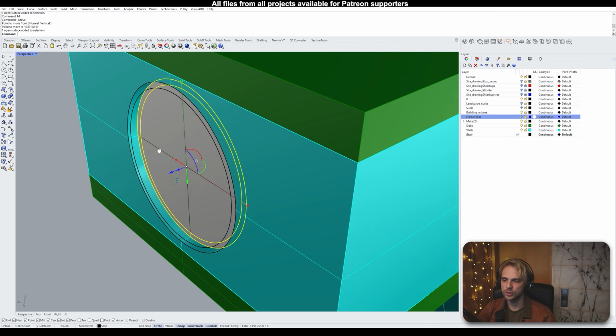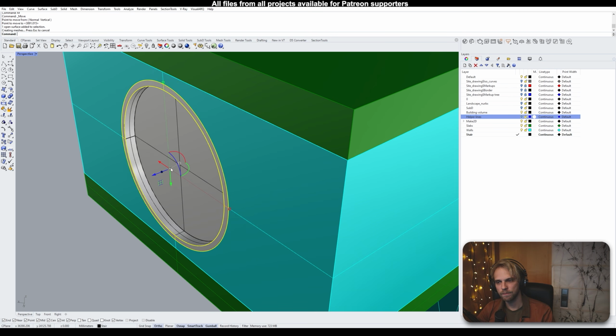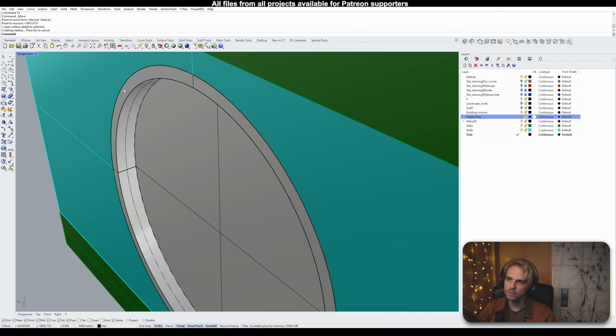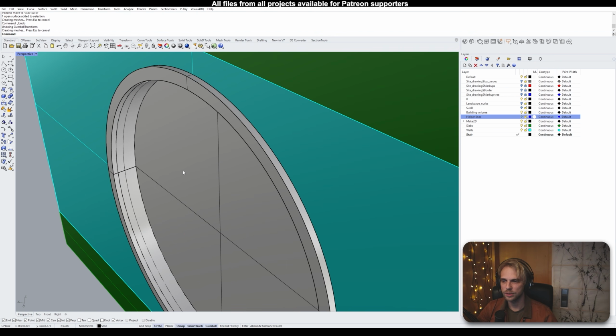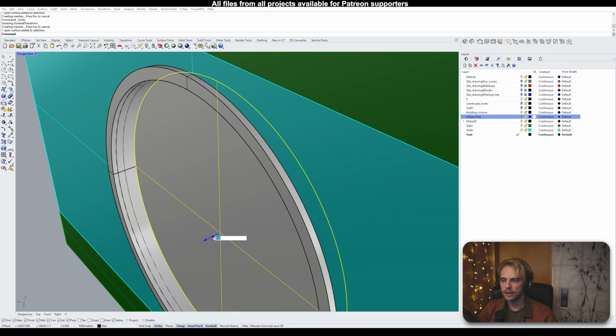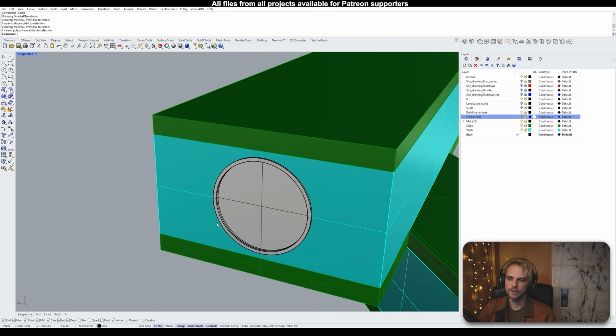And now it's time to extrude. So we select the frame, we extrude it by, well, we can do 200 millimeters or even more. I kind of want it to protrude a bit more, so let's do 250 millimeters, and the glass is 20 millimeters as per usual, and it gets moved inwards by 125, something like that.